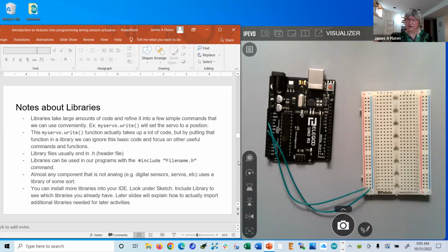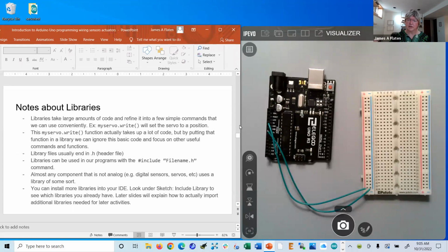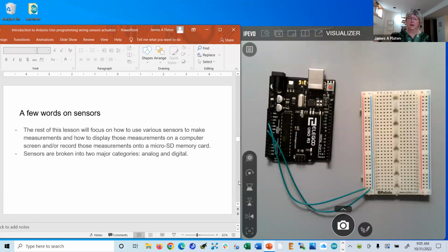I'm going to intentionally not include a library just to see it fail and then show you how to find the library and include it. Oh, did I go back too fast? Right. So this thing here suggests, at least for this version of the Arduino IDE, how to find the libraries. And I already did this one time. Go to Sketch and then take a look at the Include Library option, and it will list the libraries you have. And if the library you're looking for is not on the list, then I'll show you in a moment how to get it there.